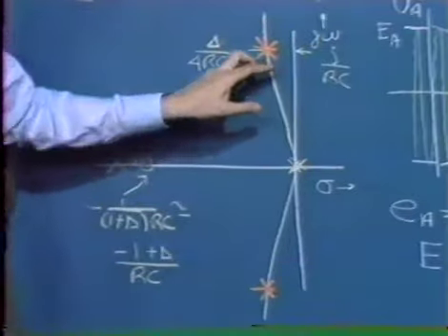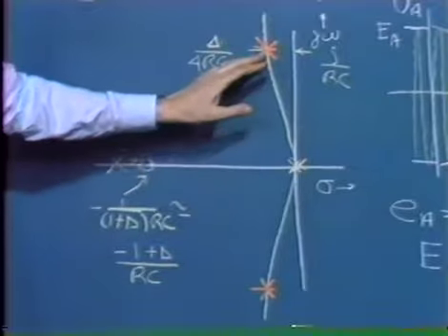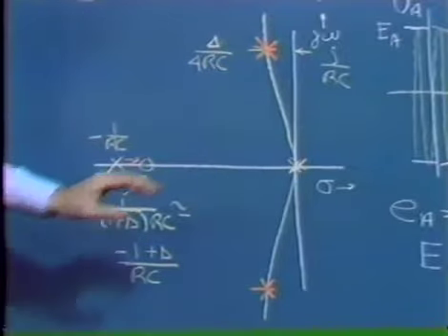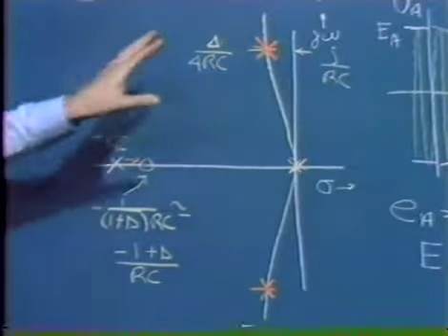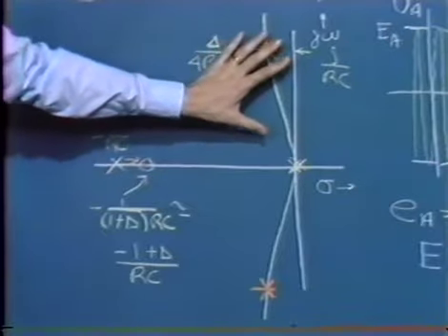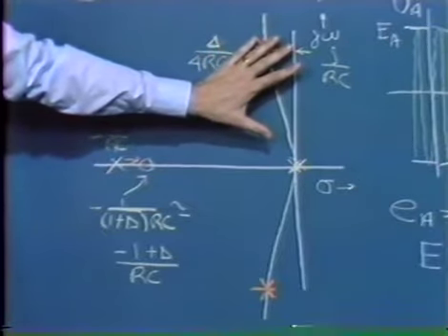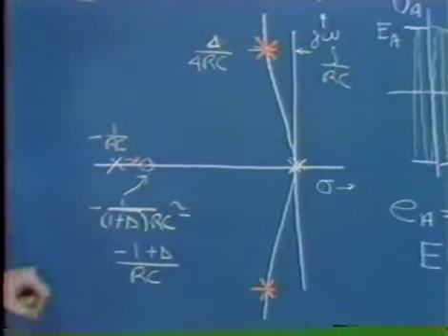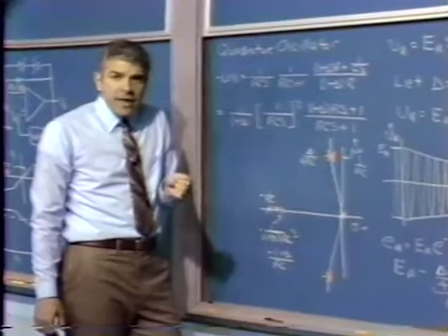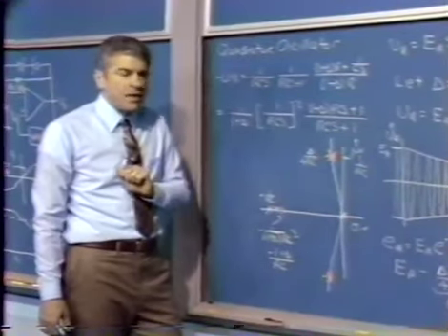And so now our strategy parallels that I suggested for the Wien bridge. We can look at the amplitude of the oscillation being generated by our system, and we effectively have a pot that changes delta.